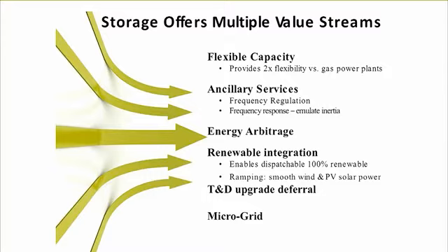Another important topic is that as the grid ages and one notes that it's time to upgrade resources, a possibility is that maybe we don't have to upgrade resources. Say we have an isolated part of a feeder, and the feeder is weak. In order to meet the peak load, one could install energy storage instead of increasing the capacity of that feeder.